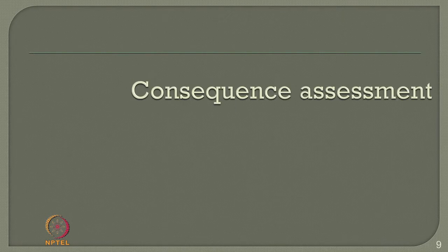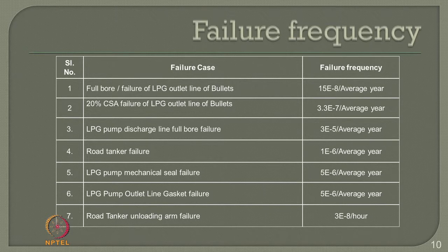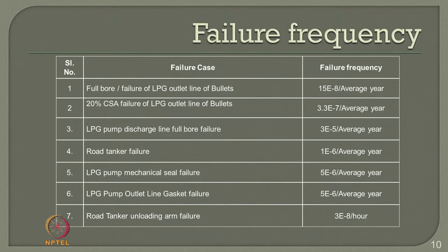Now we wish to do a consequence assessment on these kinds of problems. So failure frequency becomes a very important input for such analysis using a software. Let us try to understand what are the possible failure frequencies which may arise from a full bore failure, a 20% cross sectional area failure, LPG pump discharge, road tanker failure, LPG pump mechanical seal failure, LPG pump outlet line gasket failure, or road tanker unloading arm failure. One can ask an interesting question: how do we fix these kinds of failure frequencies? Of course, there are two methods by which these failure frequencies can be arrived at.